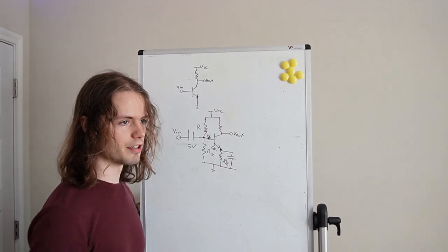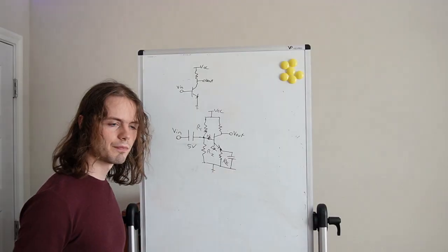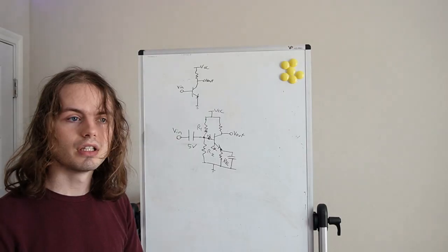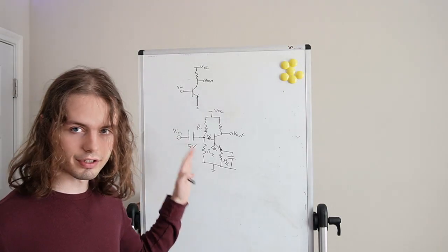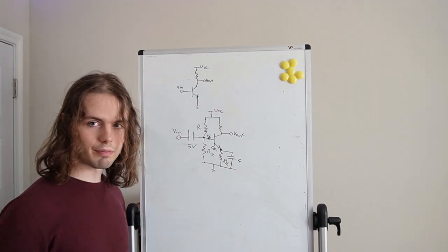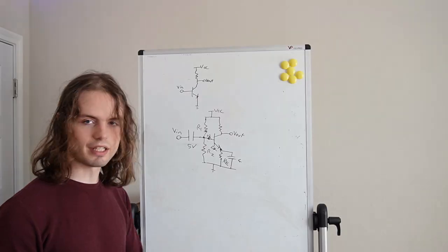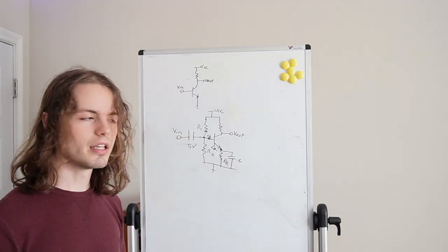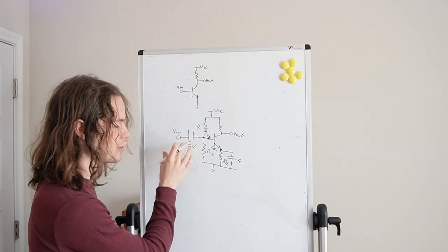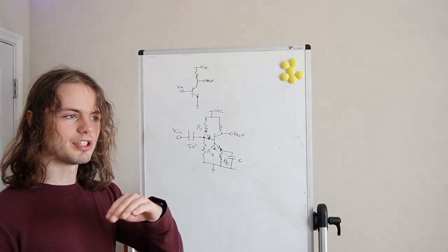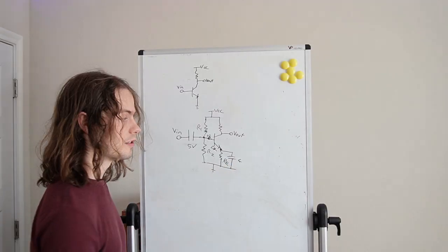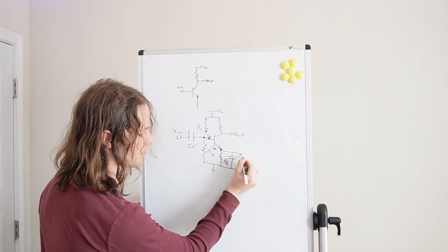As for this capacitor here, if you have this emitter resistor, it will decrease the current that is allowed to flow through the system, because if you increase collector current, it would cancel out. That's why the capacitor is here, because since you're trying to pass an AC signal, you don't want to deteriorate it. You're trying to amplify it. And when you provide a capacitor here, similar to the first capacitor, it acts as a separate path for AC signals. And if you choose the capacitor value right, this path can be very enticing. It can be very low.